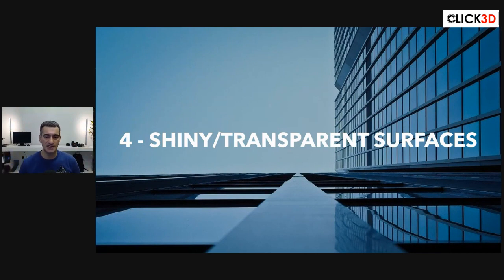I just can't use shiny, transparent surfaces. They give you all kinds of issues. And that's very clear, for example, when you're scanning something like a car. The laser scanner has a slight advantage when it's shiny. So dark, black, shiny vehicles are a problem for photogrammetry, and they're a problem for laser scanners. But laser scanners will tend to give you better data. So in this metric, for shiny, transparent surfaces, I would give the laser scanner a little bit more of an advantage over photogrammetry. With photogrammetry, you end up with a big mess. And at least with the laser scanner on a shiny surface, you can kind of get something.